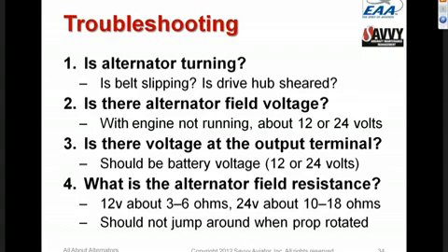If we are seeing voltage at the alternator field terminal and we are seeing that the rotor is turning, then we know we have a bad alternator and we're done. And if it's outside the alternator, we have to keep tracing back with our meter until we find where the problem is. Might be the regulator, might be the wiring, might be overvoltage relay or alternator field switch or circuit breaker, whatever, but it shouldn't take very long to figure out what the culprit is.